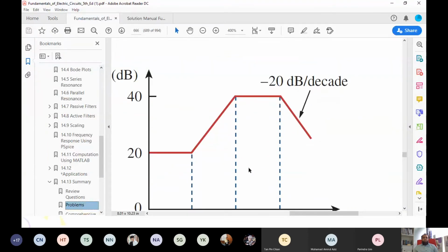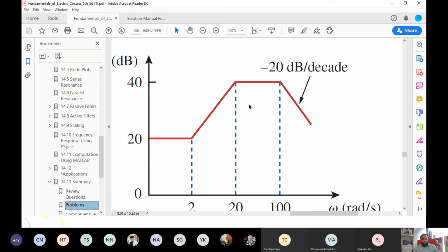All right, let's say I give you this Bode plot. Remember, each line means something. An initial constant at the beginning means this is the constant gain. If something is going up, there is a zero. If there is a flat line after that, the effect of this zero is being cancelled by a pole, plus 20 dB, minus 20 dB. This is happening at some particular frequency.